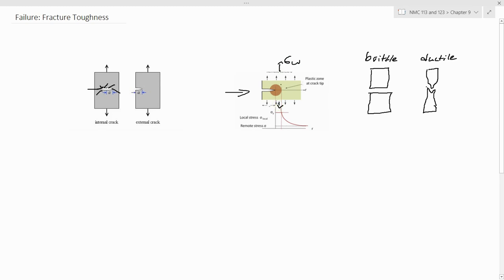Now once you get to the tip of the crack, because this tip is a sharp edge, it has stress raisers, meaning that the working stress is amplified. So you have a localized stress. The stress being exerted here is the working stress plus the localized stress facilitated by the stress intensity that comes with the sharp edge, right?